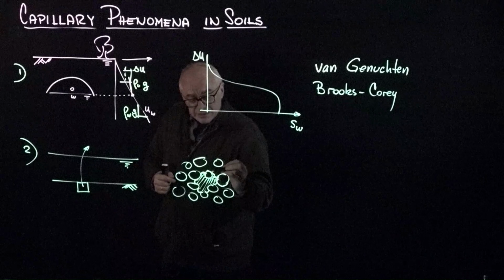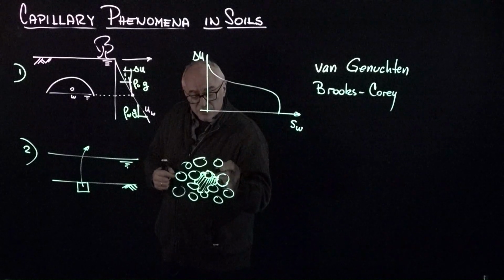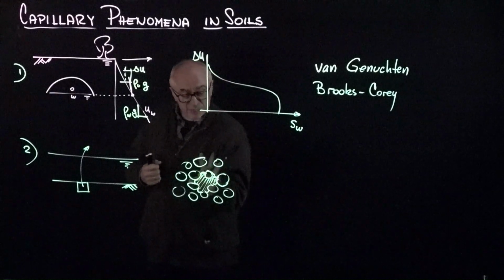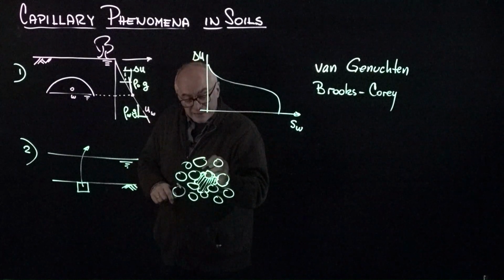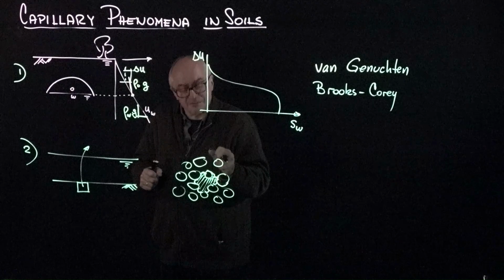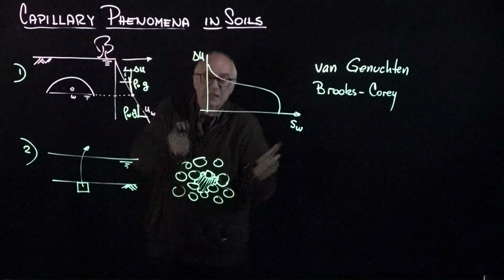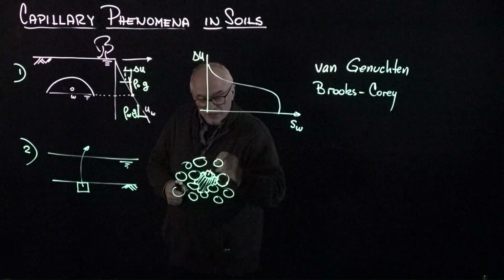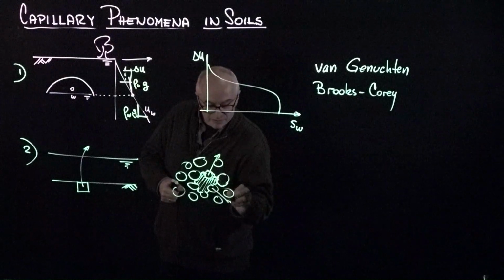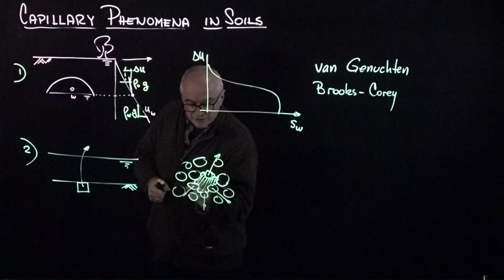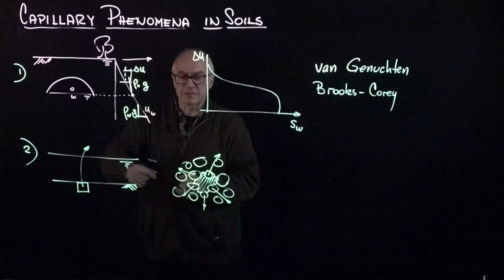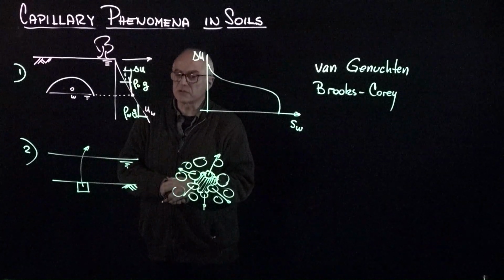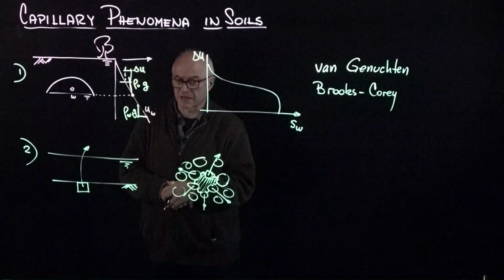And so the particles experience two things: the gas pressure greater than the water, which is pushing them out, and the menisci that are grabbing the particles, and the interfacial tension is also pushing them out. So these particles are being pushed away from the gas bubble, which means that by the time we take this specimen to the surface, it's going to be significantly destructured.